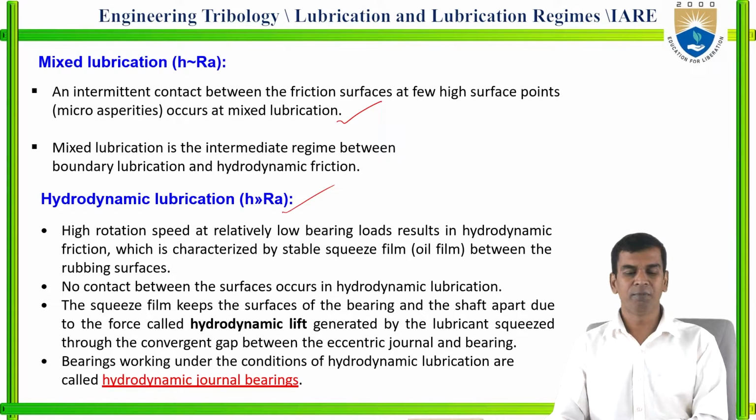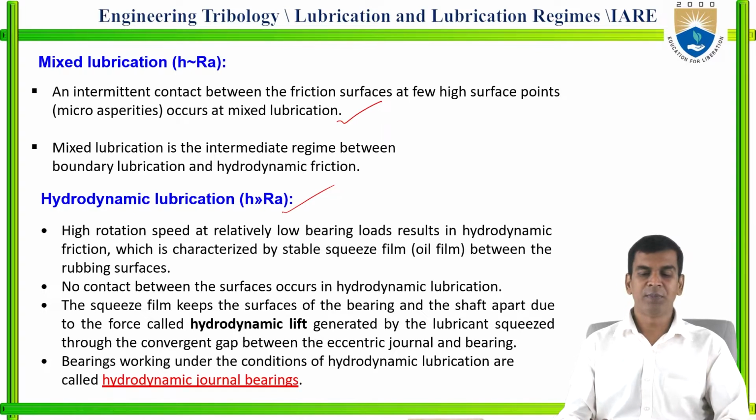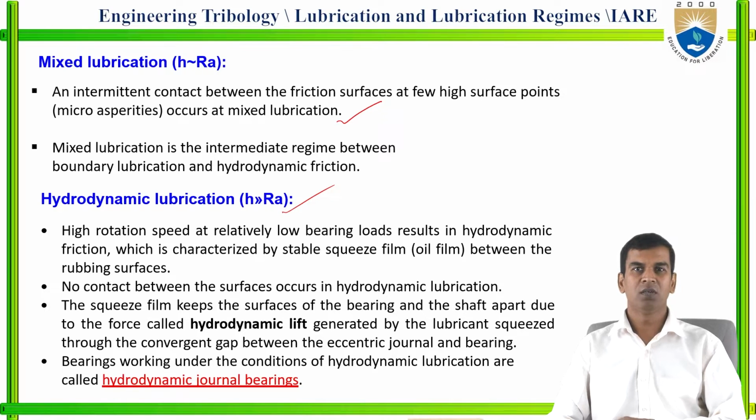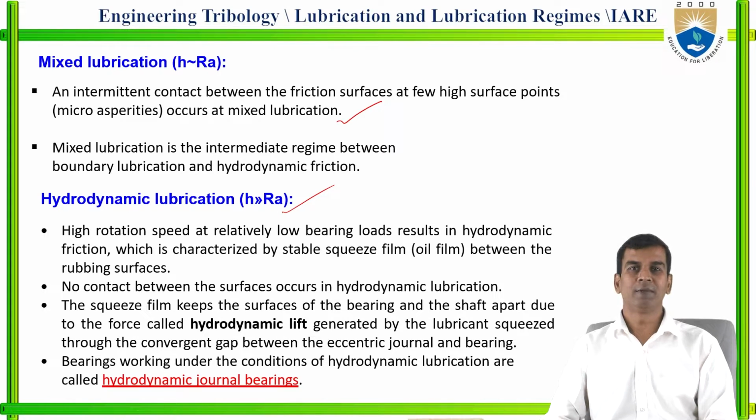The squeeze film keeps the surfaces of the bearing and the shaft apart due to the force called hydrodynamic lift, generated by the lubricant squeezed through the convergent gap between the eccentric journal and the bearing.